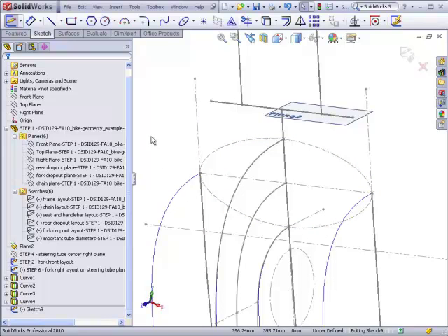The reason is that when you do a sweep with guides, the profile sketch needs to have Pierce relations to all of the guides. Because this oval was drawn before the guides, it has no Pierce relations to them. Unfortunately, what that means is that this oval was just acting as a placeholder for us to get our geometry correct in our sketches, but we have to redraw this sketch again and make proper Pierce relations to all 4 of the guides.